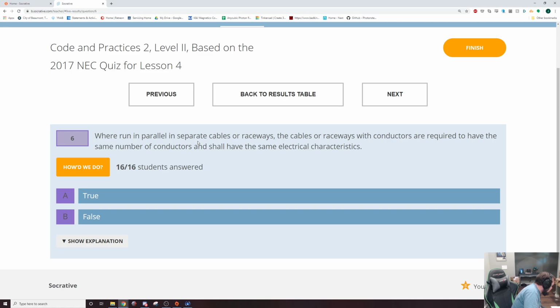There's some exceptions. So then there's 310.10H2, conductor and installation characteristics. It's important. We've done enough DC theory to know that whenever you have different lengths, they're going to have different resistances. Whenever you have different resistances in parallel, the one with the lower resistance is going to have more amperage. And that might spike the amperage up on one leg.